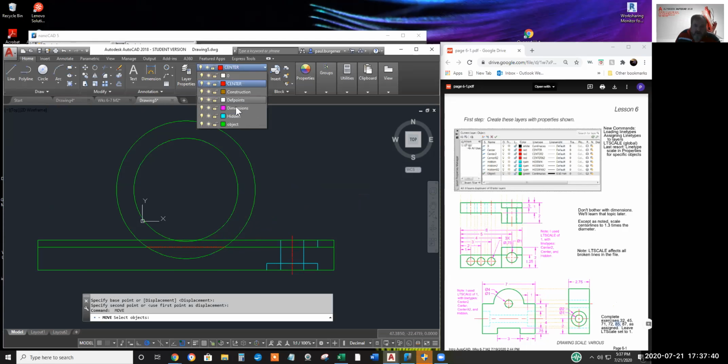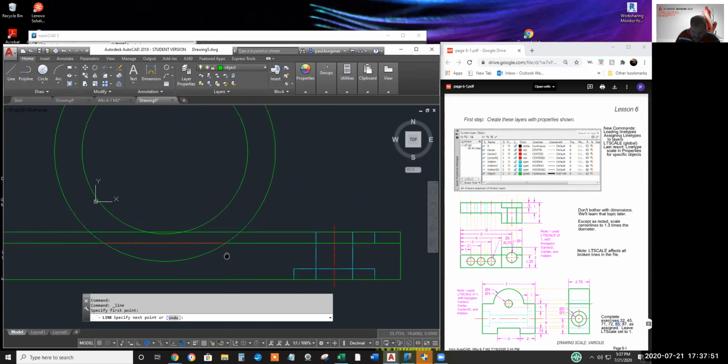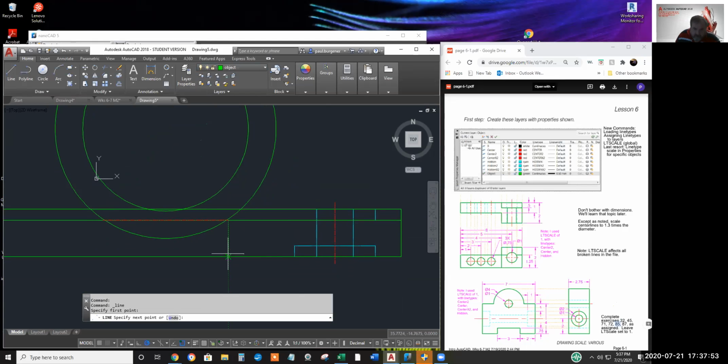Let's go to the object layer and connect the dots from the end point of the chalk line we just drew straight down to the intersection of the polar tracking line and the green line. You can do the same over here or mirror it about midpoint.